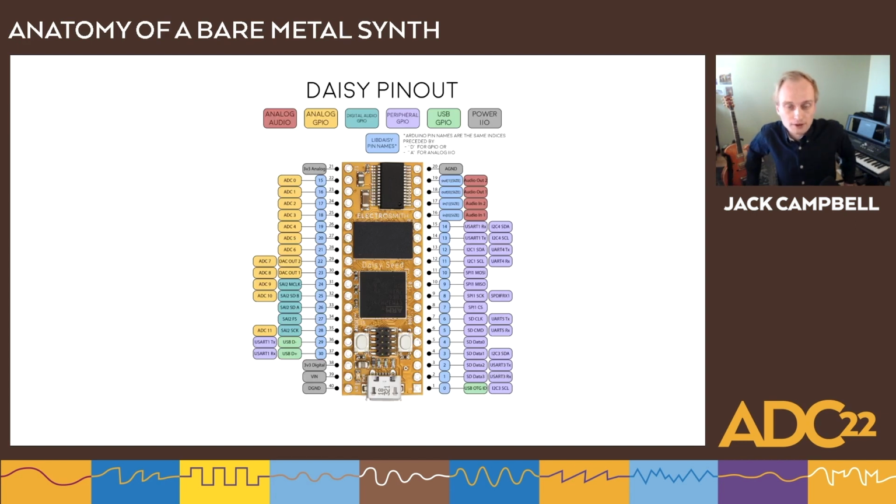And that's where the pinout comes in. A pin in an embedded context is an electrical connection between two devices that want to communicate. You can see there's pins all around the Daisy there for us to plug wires into. There's also pins, if you look at the third black box down, on our microcontroller, the STM32. That one also has pins all around it, and Electrosmith has decided how to hook our external connections up into those pins. And so our goal is to look at all of these pins and find out where we want to connect our MIDI. You can see there's multiple UART things there in the purple boxes, various UART peripherals.